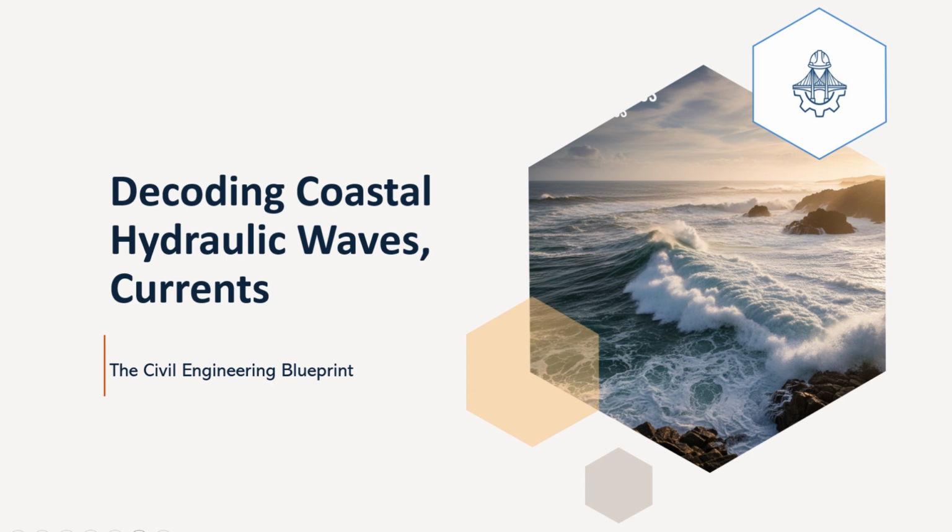And for waves, the governing principle is Snell's law, adapted for water waves. It describes the relationship between the wave direction, represented by the angle of the wave orthogonal relative to the depth contour normal, and the wave celerity C at different depths. Rearranging, sin α1 / C1 = sin α2 / C2. Here, α1 and α2 are the angles of the wave orthogonals at locations 1 and 2 with depths d1 and d2, and C1 and C2 are the corresponding wave celerities at those depths, found using the dispersion equation. This law allows us to predict precisely how a wave's direction will change as it encounters changing bathymetry.